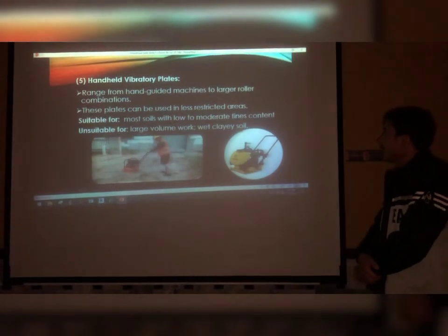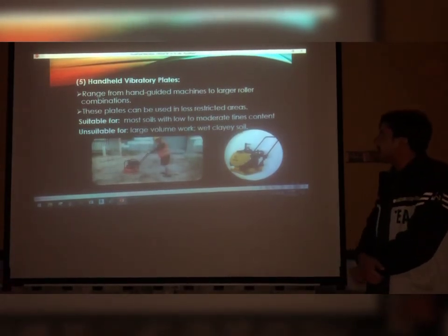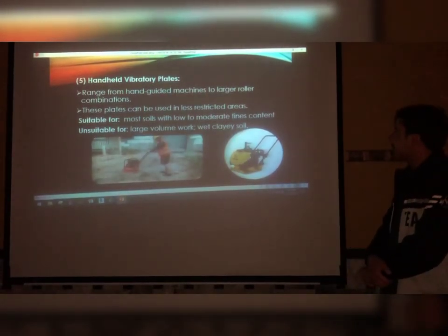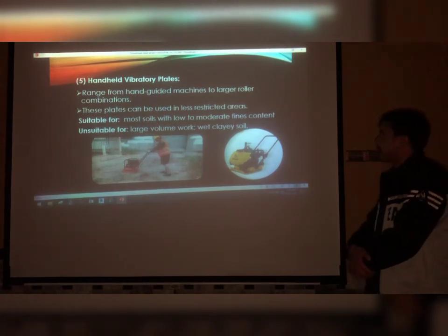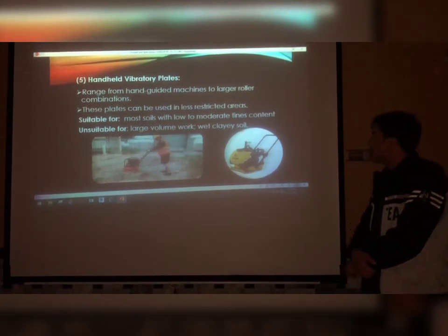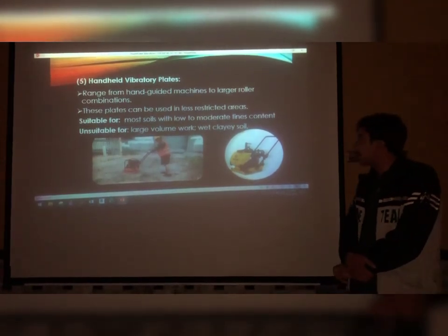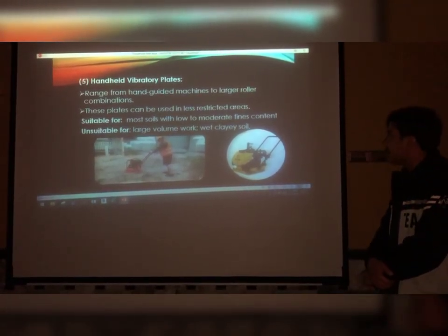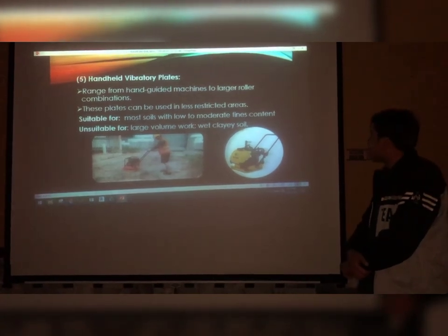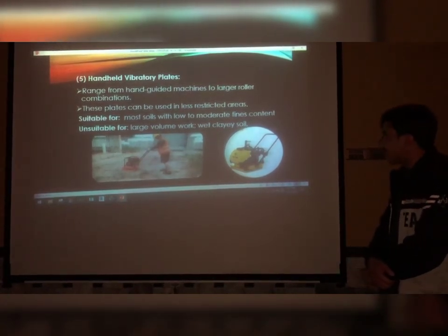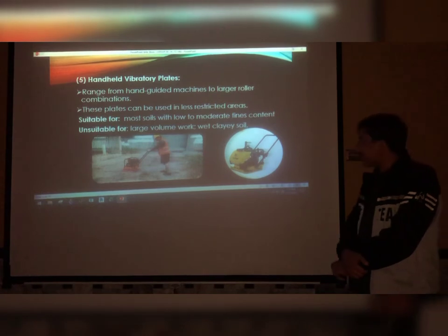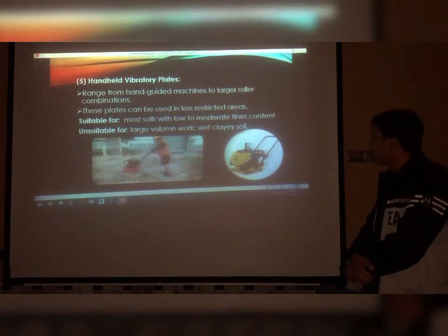The fifth one is handheld vibratory plates, ranging from hand guided machines to large roller combinations. This plate can be used in restricted areas where other types of rollers are not accessible. It is suitable for most soil with low to moderate fines content and unsuitable for large volume work because it is time consuming. Wet clay soil we can use.